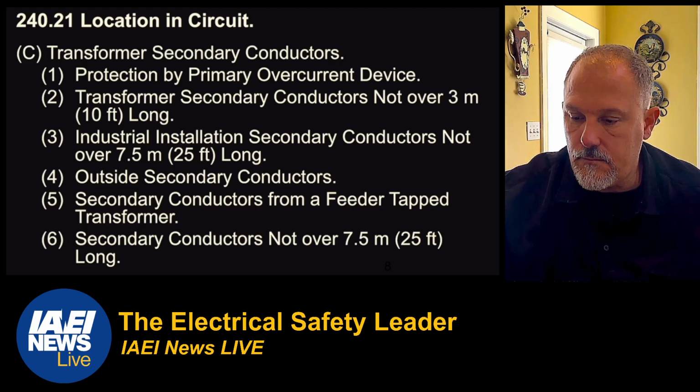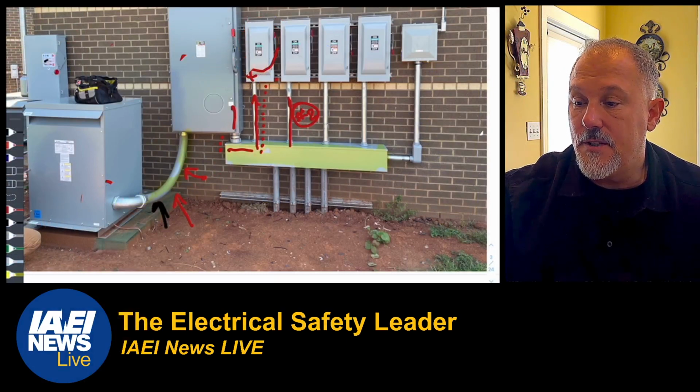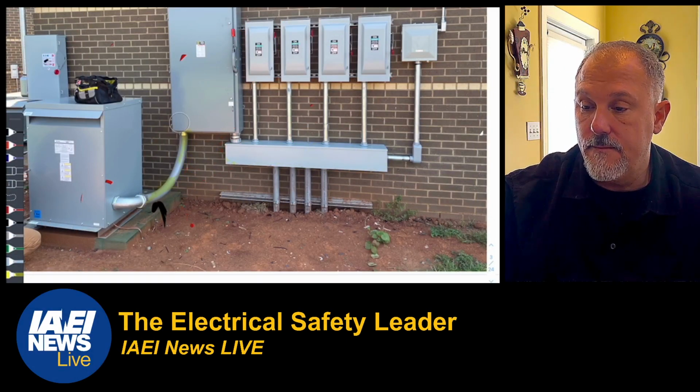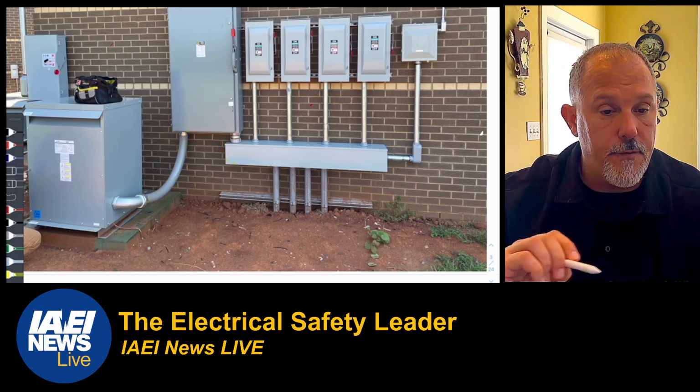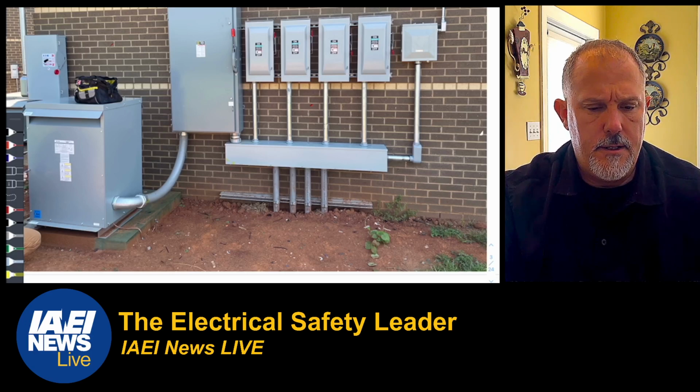All right, so if we take a look at the application again, we know this is an outside application just from the image, right? So let's take a look at the requirements. Again, we're talking about transformer secondary conductors. Let's take a look at the requirements in 240.21(C), outside conductors, 4.